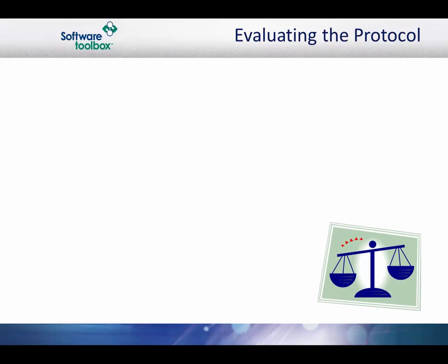The first step to determining if the TOP Server UConn driver is for you is to evaluate your protocol by asking yourself the following questions. How complex is it? Determining how complex a protocol is can be a long learning process if you have never done something like this before. In general, most of the devices you encounter will have very simple ASCII or binary protocols.